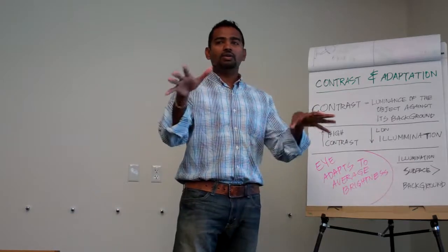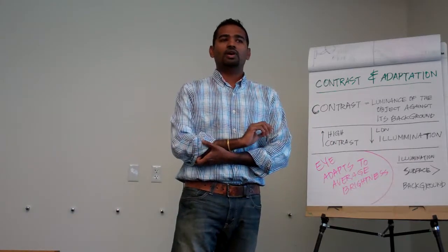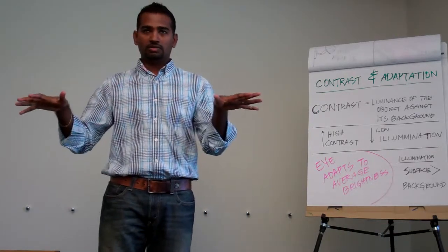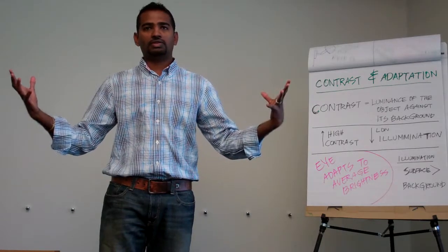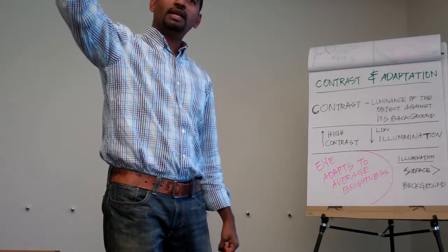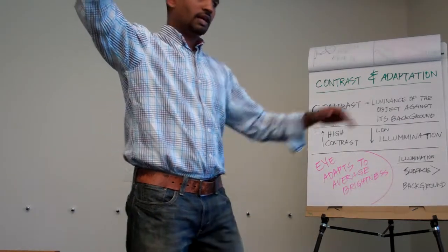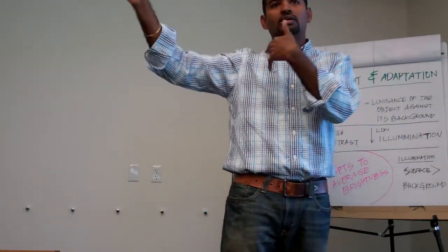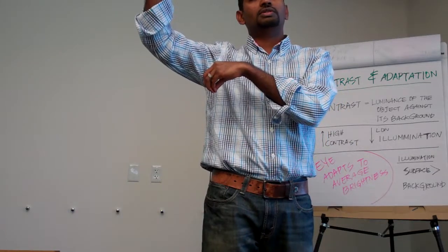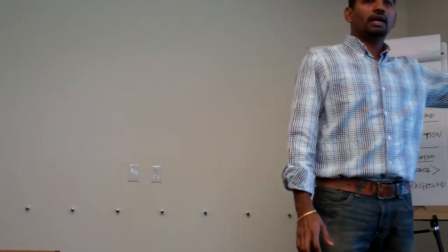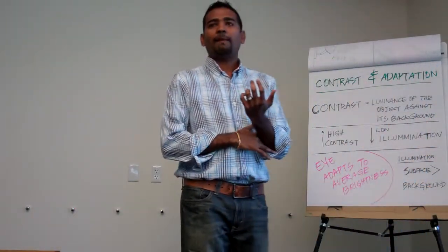And how does this impact our design? Let's say you have a conference room in the middle of the core of a building. It's usually very dimly lit, but it's got no openings, it has no bright sources. In that instance, if you go ahead and throw in a huge, very bright luminaire, then the person walking in will have a problem acclimatizing to that dark conference room with a bright light source, as opposed to having a conference room like this, where you have a brighter environment. Does that make sense?